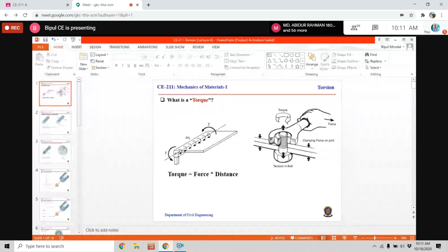So look at the first figure. It is a cantilever slab. It is supported by a beam. Do you see the cursor here? Do you see the cursor? Can anyone? Yes, sir. Okay. So this is the beam, and this is the cantilever slab. So if we ignore the live load, then due to the self weight of this slab, this beam will try to twist.